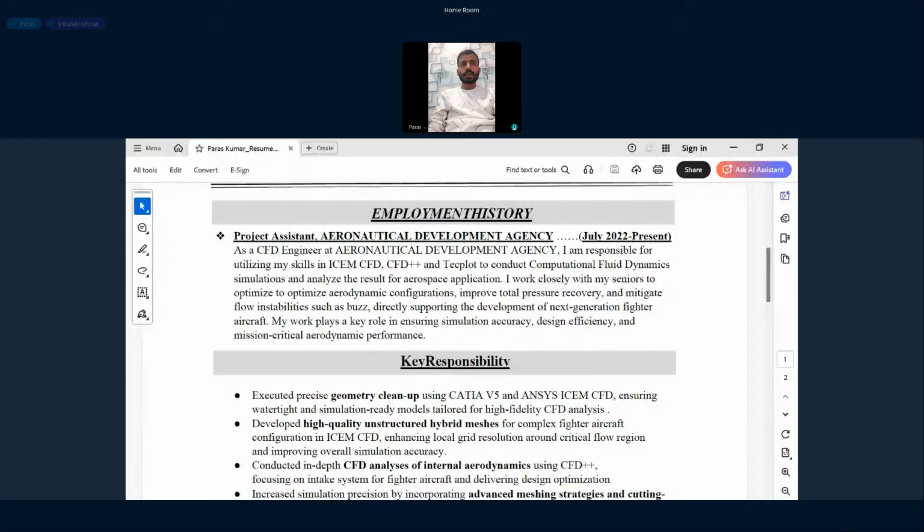Because during transonic flight, what will be the conditions in the intake? Sir, comparing to the others, when we go from subsonic to transonic, the pressure recovery will reduce, like less recovery of total pressure. Okay. And the flow will become turbulent from subsonic to transonic, right? Yes, sir. That is the main problem.